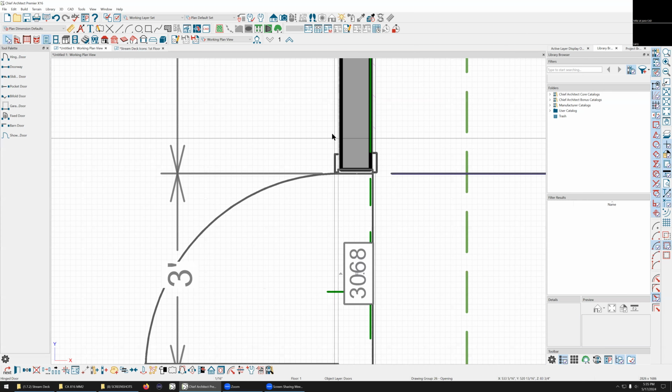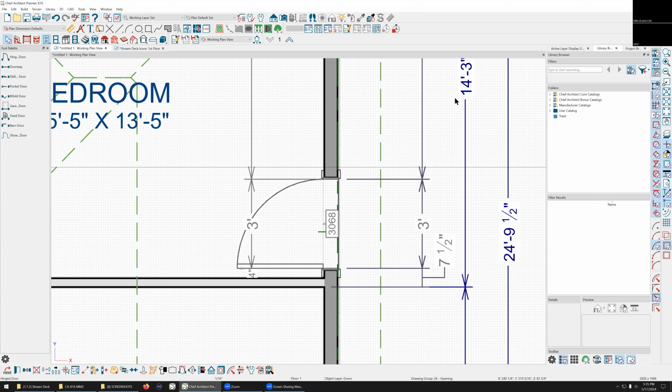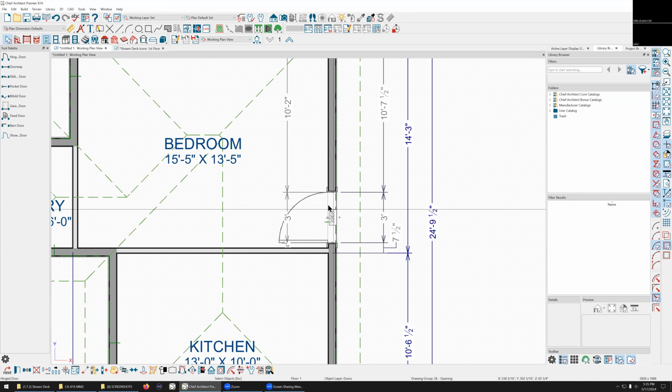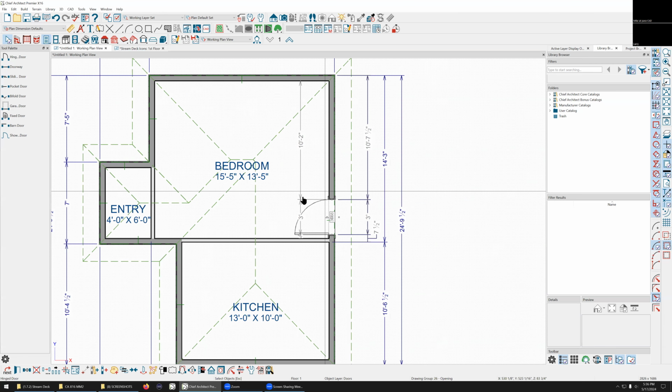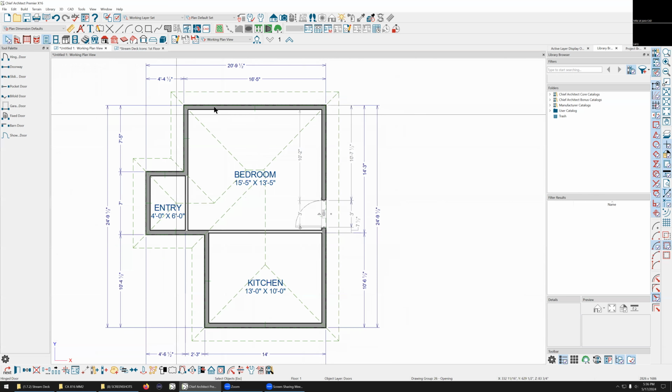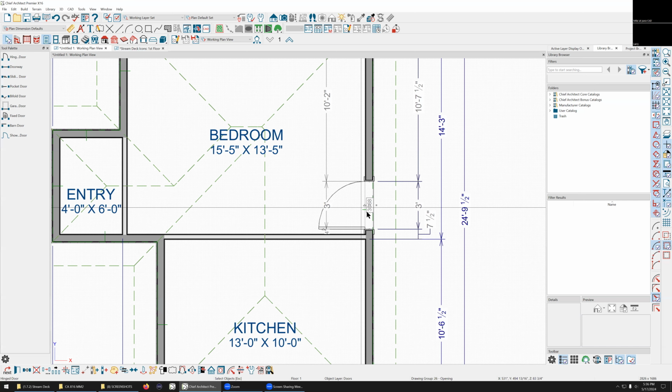Every single door should automatically have a light switch. And if you're not doing an electrical plan, you can always hide the electrical layer, but it should be right there every time you drop a door, about 6 inches off that door. And I like that because even on a sliding door or barn door, any of those, the side that you open, there should be a switch right there, because as soon as you open it and come in, you want the light switch. That's another good suggestion.